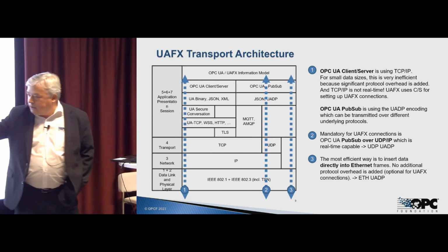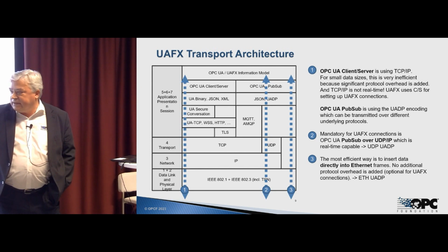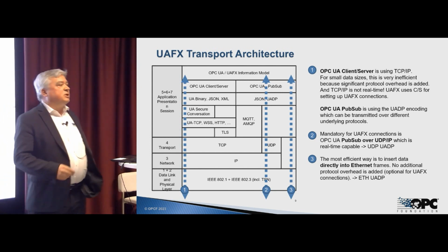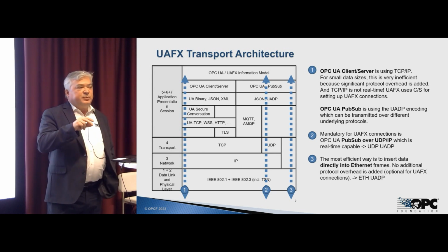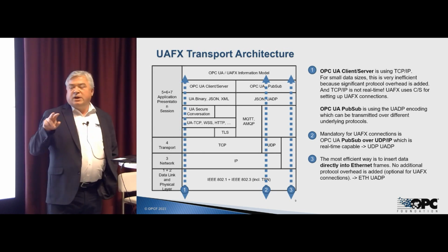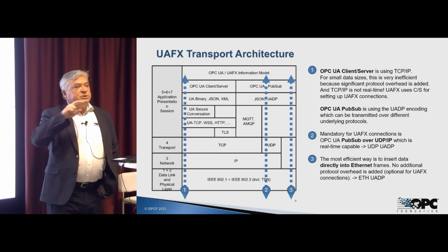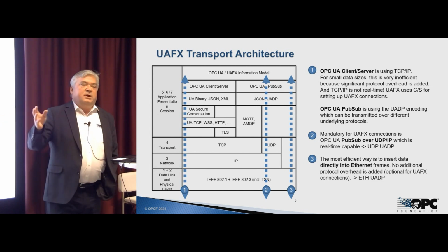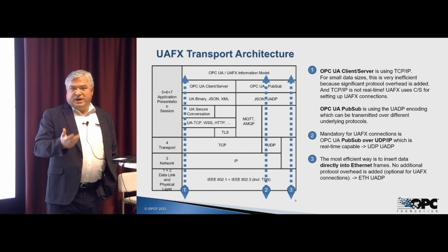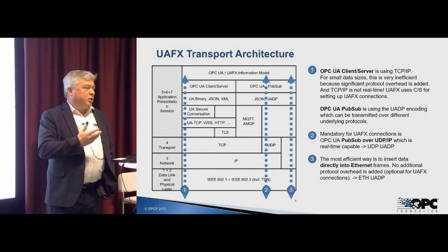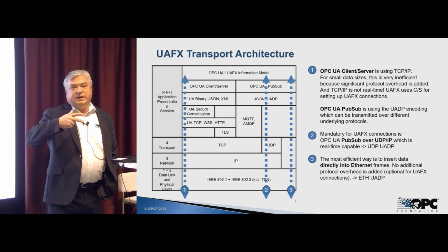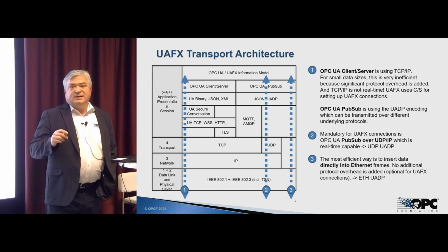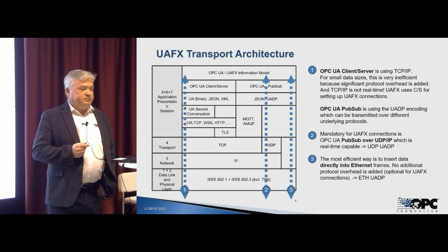If you look at the lowest layer, you still see here Ethernet mentioned, but also including TSN. And this is another aspect because we certainly have also at the layer 2 options. We can go with conventional Ethernet as we have it today, broadly accepted and used, but we also can go with the new version of Ethernet supporting deterministic transport.